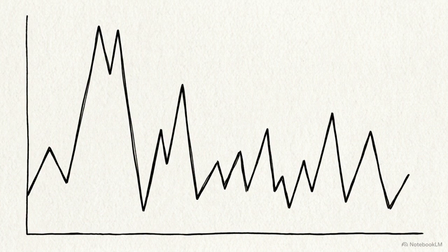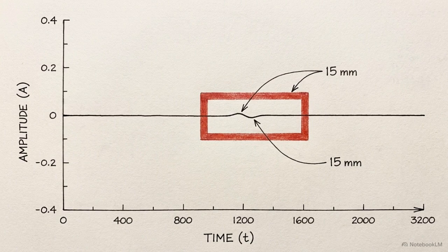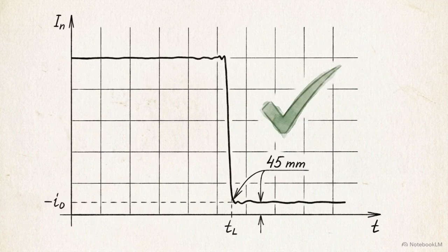The signal data does not track sequentially with the physical reality of the growing defect. This makes the Bode plot dangerous for automated diagnostics. An algorithm reading these signals could easily flag a minor 15 millimeter fault as an emergency, while ignoring a much more severe 45 millimeter shift.